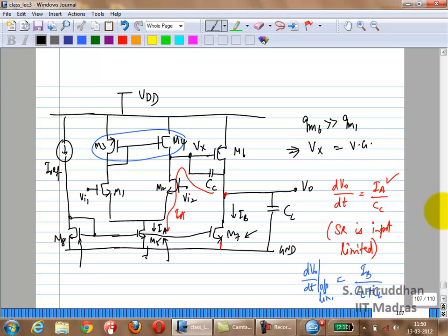Yeah, you can increase IB, for example. Well, we have fixed it, giving it the minimum value so that it doesn't meet, right? Just like we are fixing W over L of 6, assuming we meet the minimum value of VD sat, right? We have not put any other constraints. So in reality, this is just a first cut design. You want to make sure you meet everything, and then for the first cut design, you need to go back and make certain checks.